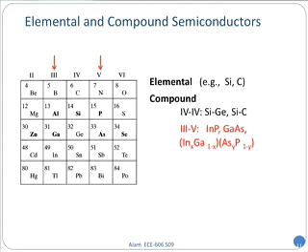That used to be a red laser, which is gallium arsenide based, but all telecommunication lasers are indium phosphide based. You can also have a more exotic combination like indium gallium arsenic phosphide, again from group 3 and group 5. Each one of them, of course, has different properties. We'll get to that a little later.